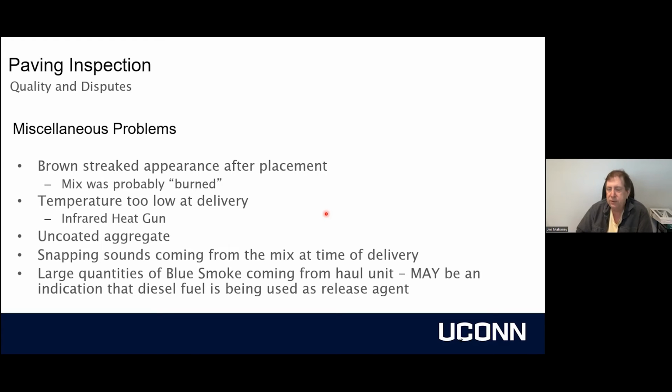We can also have situations where it literally sounds like Rice Krispies when you add milk to them, where you get snap, crackle, pop. What that is, there's still moisture in the stone and the sand, and that snapping sound is actually the steam popping through the asphalt coating. And you can actually hear that out on a paving project. Again, something that we want to be aware of and try to correct before we place down thousands of tons of this material.